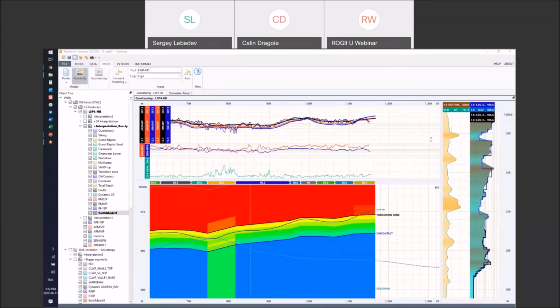Would be impressed if you have this function to do a 2D forward modeling in Starsteer for horizontal oil-water contact and up dip information as shown in slides. Right. So I can answer that. So 2D forward modeling, we cannot support it yet, as we cannot do the thickness changes. I mean, we can do the thickness change in a standard geosteering model, but right now it's not supported in the resistivity model. We would be able to do that in future.